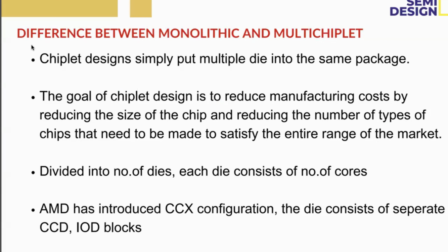Multi-chiplet is nothing but a number of dice on the same package. Based on the configuration and specification, we will divide, based on the CCX or IOD, the number of cores and number of dice, we will make the partition.